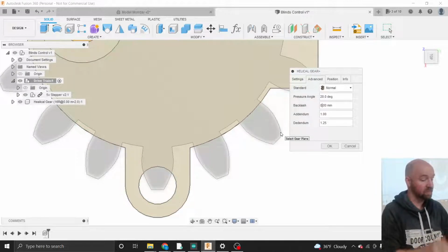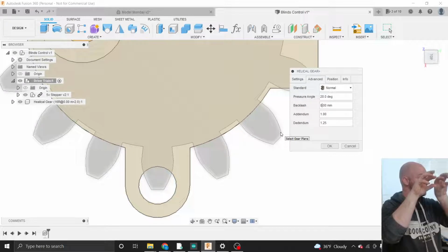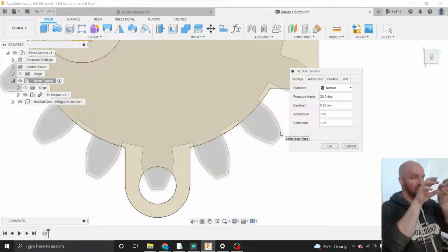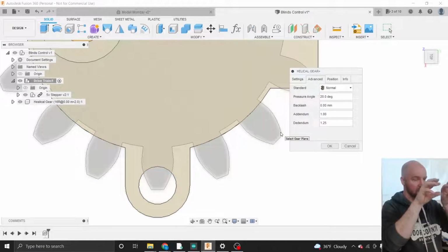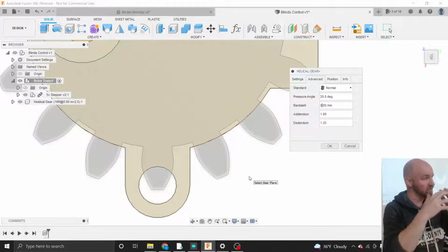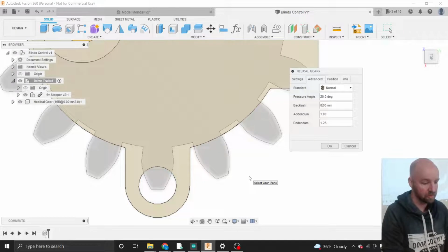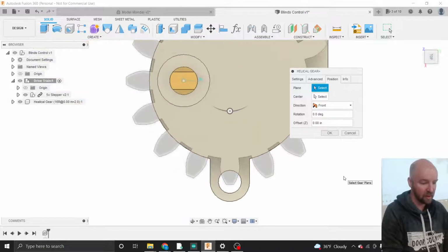The 3D prints end up shrinking a little bit, and I find that the amount of shrinkage I get on each side of the gear, when there's two gears meshing with each other like we're going to have them, gives enough play in between the gears that they move around really nicely.